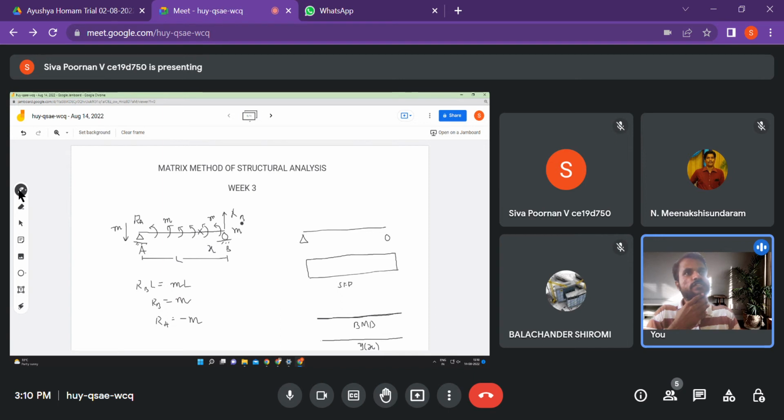shear force. We know that differentiation of bending moment is what is shear force, right? There might be a negative sign depending upon the sign convention, but let's say that magnitude wise the differentiation of bending moment is what is shear force, right? Then if I have bending moment itself to be 0, its differentiation is definitely 0 along the span. dM by dx is 0, right? Then how come shear force is finite constant here? Shear force should be 0, no? According to this formulation, is it not?